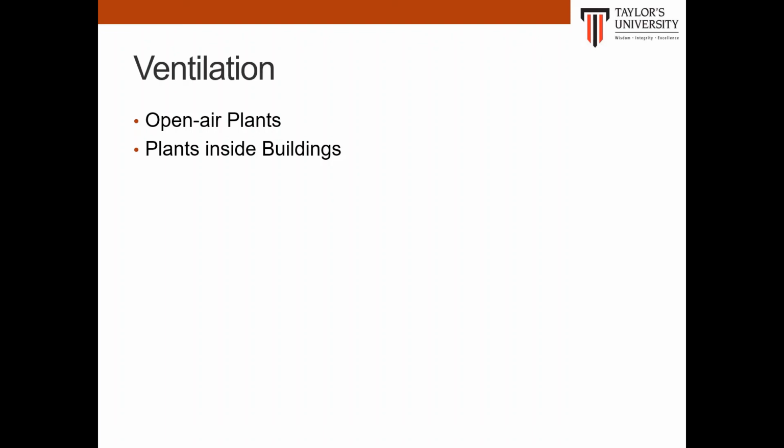Dilution ventilation, however, is also used because the potential points of release are usually very numerous, and it may be mechanically or economically impossible to cover every potential release point with only local ventilation.